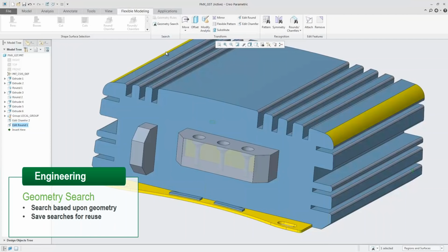If you're wanting to go through a step of simplifying your geometry for CAE analysis, typically you're going to have certain rules around the type of geometry that you want to remove. You want to remove rounds of certain size. You want to remove holes of certain size or pockets. Now you can store all that information away as a search inside this recipe file that you can then retrieve back at a later stage to simplify the model down to run your analysis against.